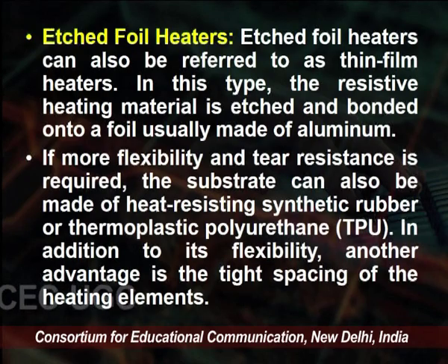synthetic rubber, that is a thermoplastic polyurethane, that is TPU. In addition to its flexibility, another advantage is the tight spacing of the heating element, and this is the inherent advantage of photochemical etching. Even heat distribution with a larger heat density can be achieved in such small forms, and its applications are more specific in comparison with the conventional wire heaters.